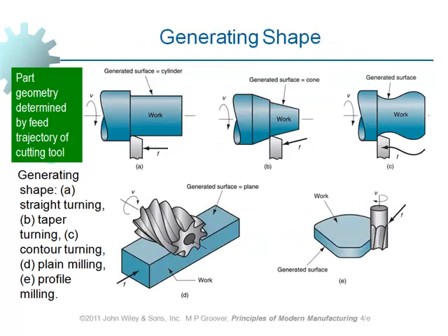Let's move on. Here we can see a number of machining processes, starting from A, where a rotational machine part is being produced, and if you take a look at the cutter, it makes a straight motion, which is called feed, in order to bring the part to final shape and geometry. And it's the workpiece which rotates, which can be performed on a turning machine, right? How about the one at B?